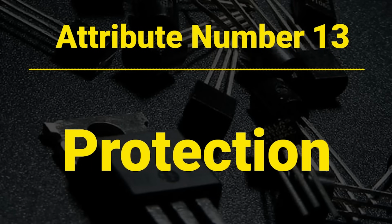By the way, some regulator ICs need plenty of external components which makes using them difficult, while others need a few external components, mostly an input and output capacitor only. Attribute number 13, protection. Last but not the least attribute is protection mechanism. Some voltage regulator ICs include built-in mechanisms for protecting the regulator itself from excessive heat, overvoltage, overcurrent, or short circuits. The more these mechanisms, probably the more suitable the regulator to use and the more expensive. You can consider all these attributes and select the right voltage regulator for your circuit.